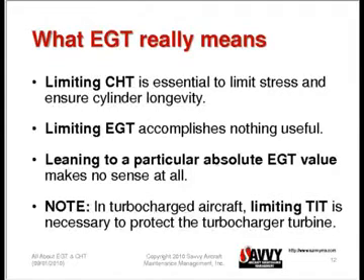Therefore, limiting CHT is essential in order to eliminate stress on the cylinder and to ensure that the cylinder has a long useful life and doesn't wind up requiring cylinder work on a frequent basis. By limiting CHT, we're limiting stress on the power assembly.